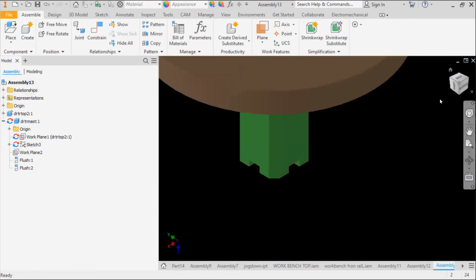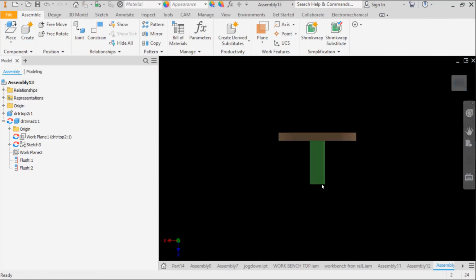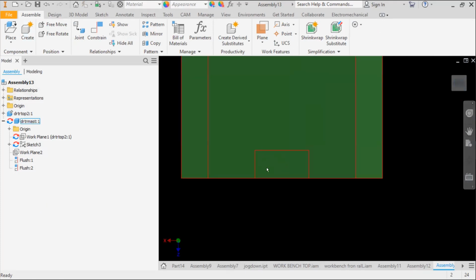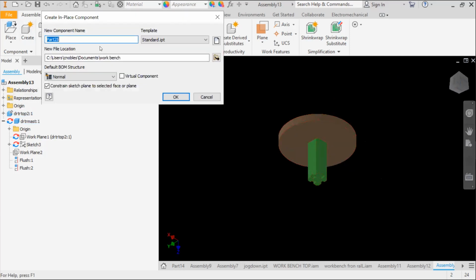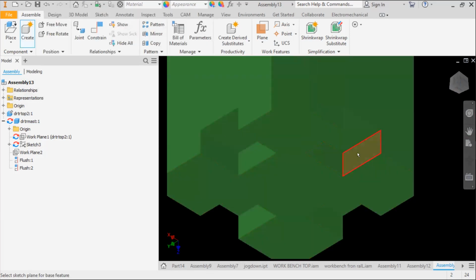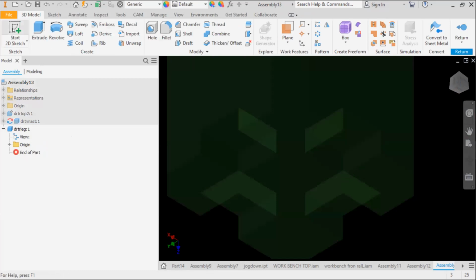The leg is a little bit trickier, okay? What I'm going to do to start out with my leg is an extrusion that comes out right here. But notice, all these parts, they're not grayed out. They're still here. We're in an assembly. We need to create a new part. Come up here to create. Dining room table race leg. Click OK. Come in here, grab this surface.